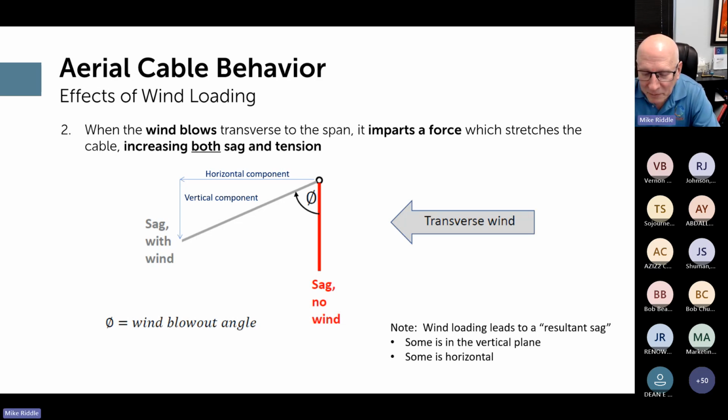And I really mean that. If it matched, great. Other questions? I see one written in chat: ADSS has very little thermal elongation, but stretches a lot more than ACSR in response to ice and wind. How do folks design the ADSS underbuild to stay in the same easement as the distribution?